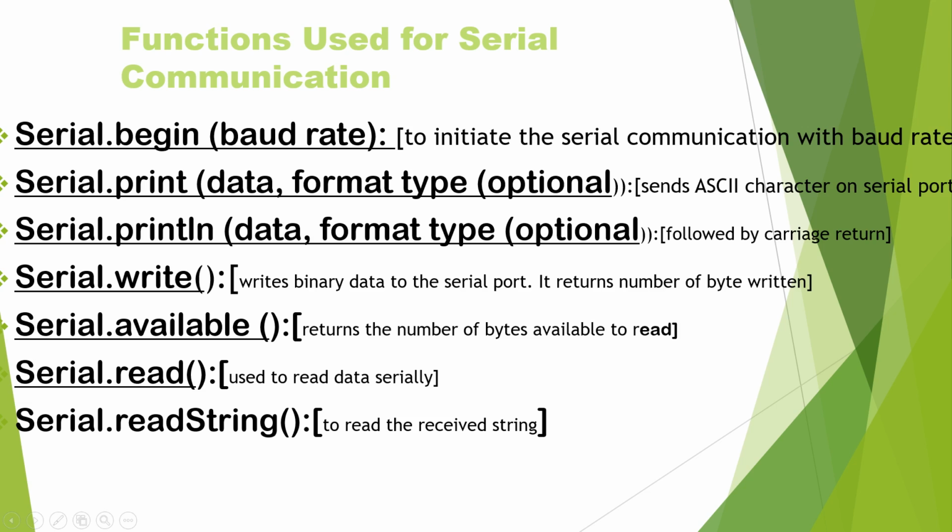Last one: in some projects I may need to read the string, not the character one by one. So this is the basic difference between Serial.read and Serial.readString. Serial.read takes one character, but Serial.readString takes the whole string. So this is the difference. Then it is enough. I am going to utilize all such functions in the demo project.